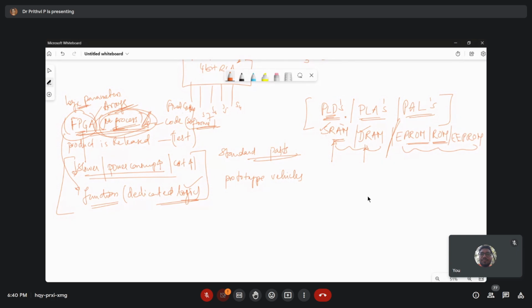How we address them is different now, and the way we store the data characterizes them into SRAM and DRAM, static RAM and dynamic RAM. In static RAM, the data will be stored in the form of a D flip-flop. Normally, a D flip-flop is a storage element, a register. In dynamic RAM, charge will be accumulated. This is the basic difference.